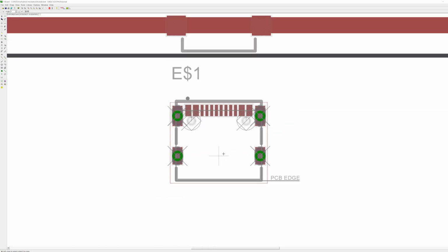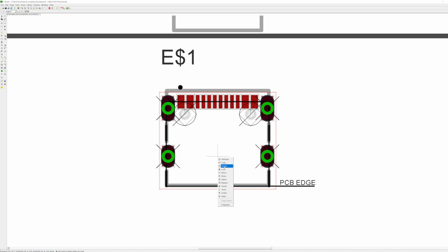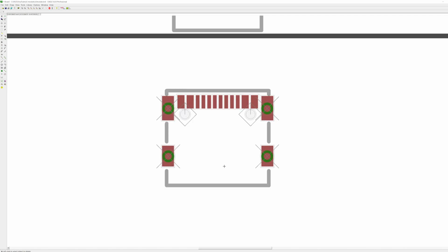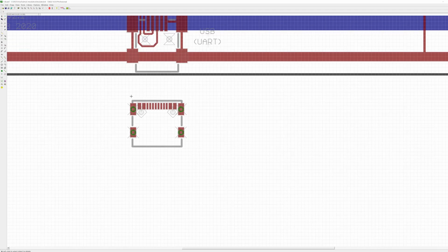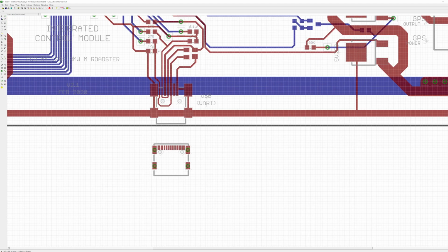So now if I scroll out, I should be able to just delete this. And now what you see is basically the Paint or Photoshop version of the exact same thing. And let me change the grid back to something like 0.025. So we have a much rougher grid. But yeah, so now with this saved in the file, I can copy it. Actually, let me do it this way. So now I can say copy group, and now I can place another USB-C connector there,